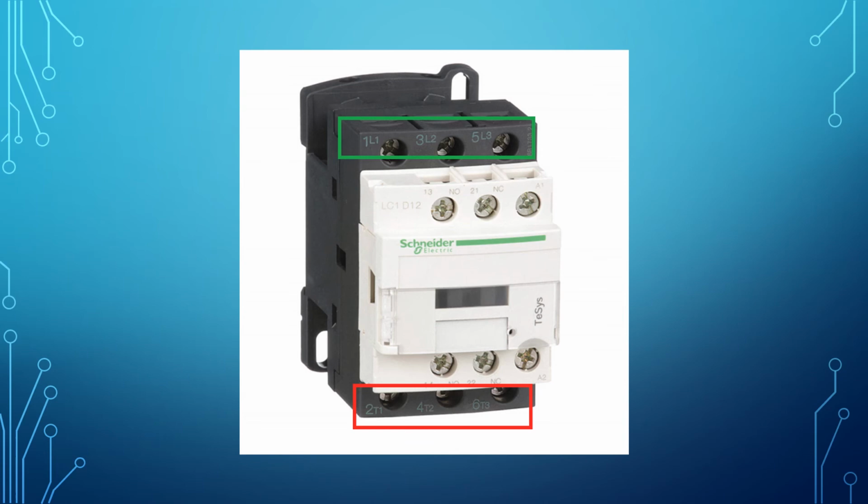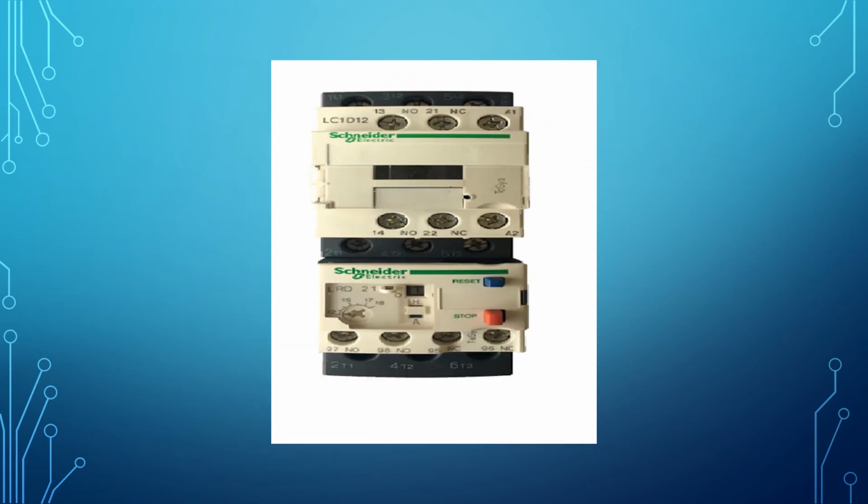If the voltage in T1, T2 and T3 is matching the three-phase voltage, then the overload terminals T1, T2 and T3 will be tested by the voltmeter. If the voltage is not matching the three-phase voltage, then the overload should be replaced, otherwise the problem will be in the cable, terminals, or the motor itself.